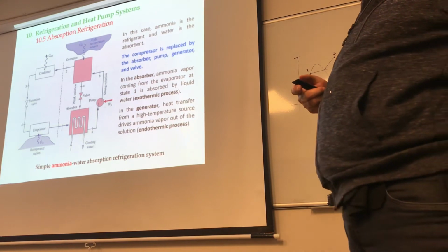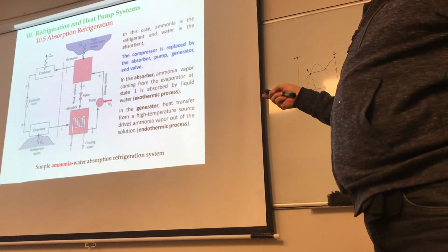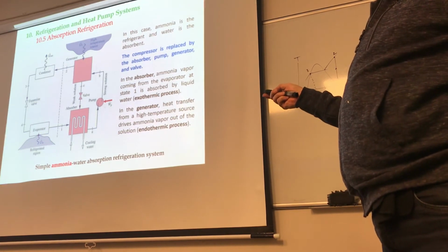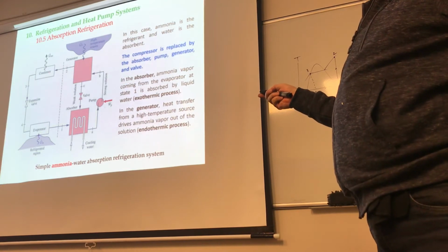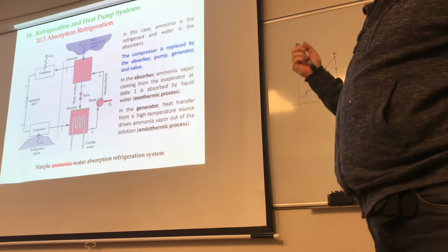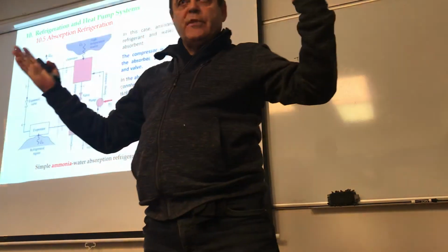Is it the liquid or the refrigerant? The refrigerant. The refrigerant is going to evaporate, and as it leaves the solution, the liquid stays. We call this the strong solution. What does strong solution mean? It means you have water that is rich in refrigerant.